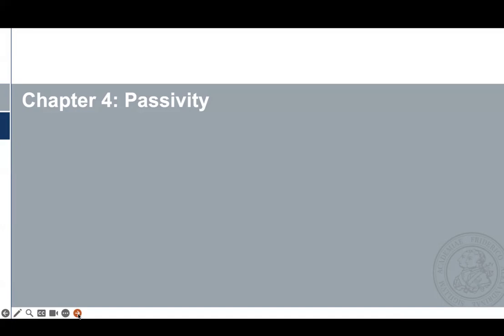We will talk about how this passive film forms and grows, and the different models used to describe passive film formation and growth. The major model that we will discuss is the point defect model: how the movement of vacancies can influence the diffusion and migration of ionic species, and thereby passive film growth.